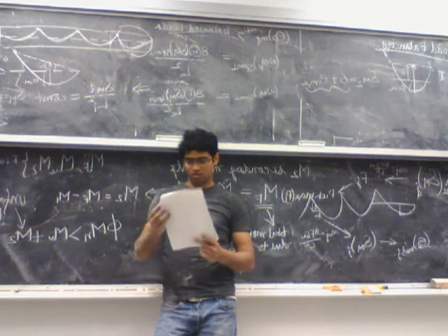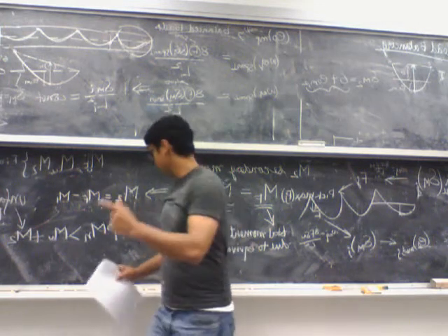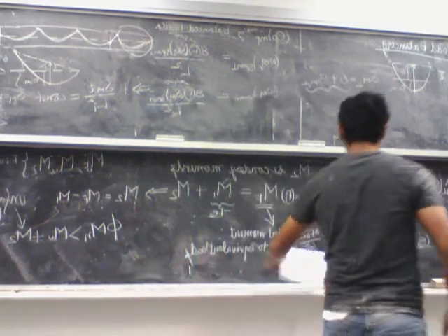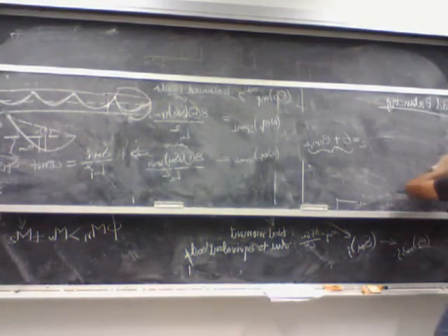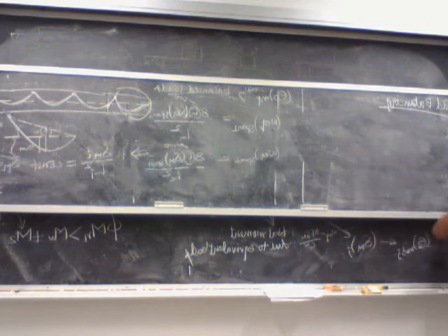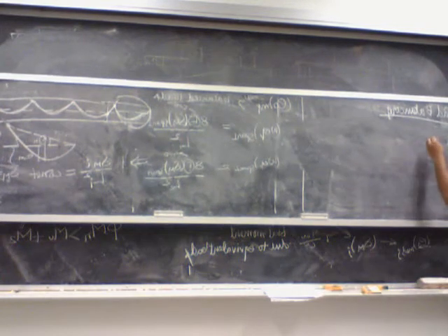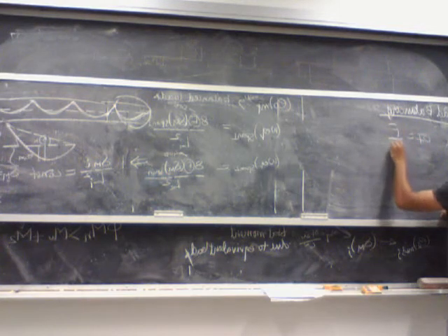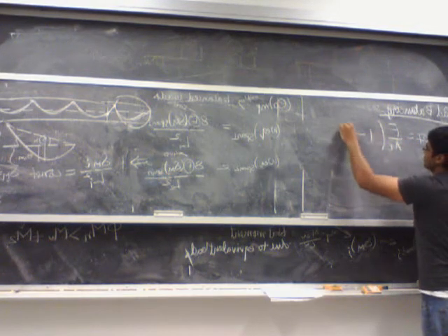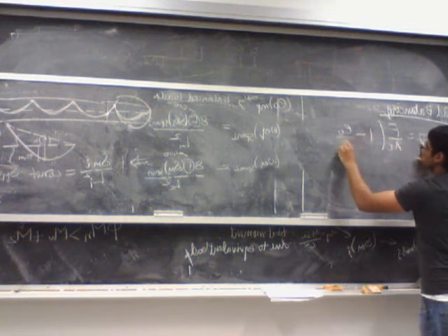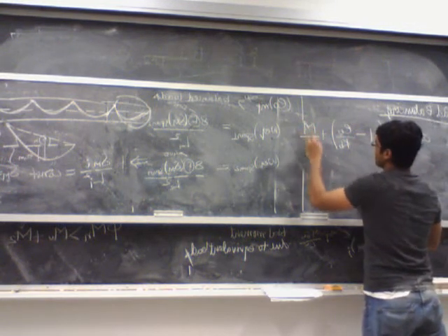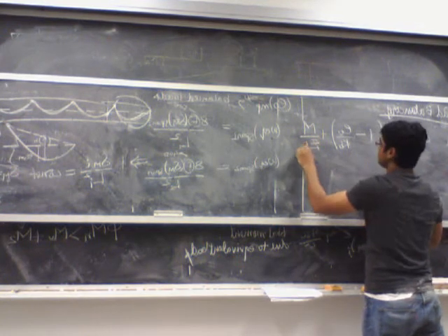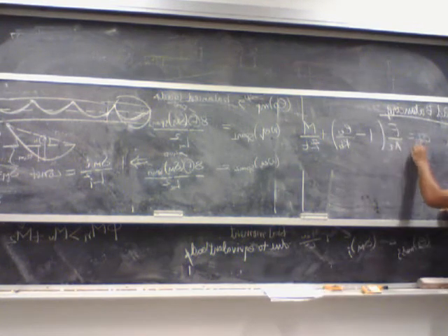Oh, the stress check. So for the stress checks, until now what we have been doing is sigma top is F over Ac times 1 minus e naught, this is top saying, minus Ab top, plus M over Zt, right?